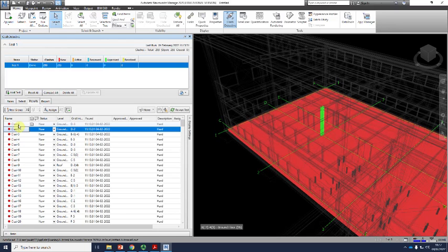Units are in here: Interface, Display Units. Keep it in meters and then convert this to 0.001. So if it's 1, it's 1 millimeter, not meter.